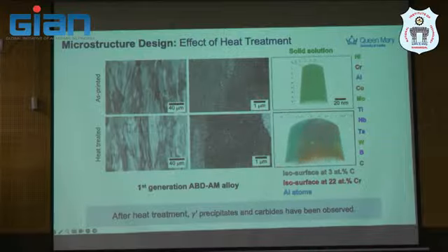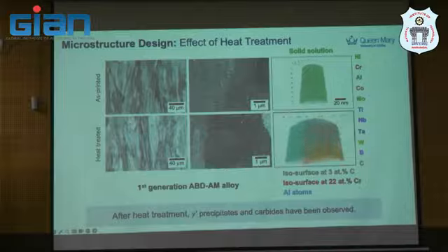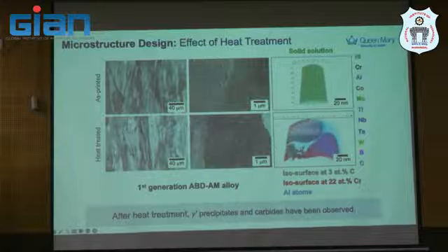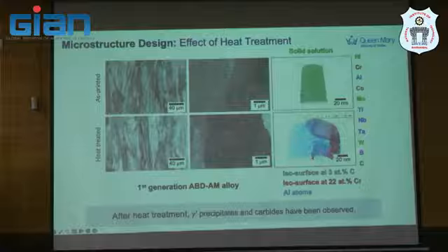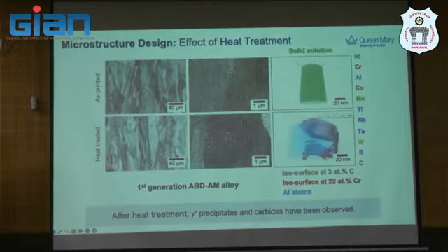We use atom probe to really map the composition in 3D, to see what happened. So there are isosurfaces of carbon, chromium, and aluminum atoms in this one. It starts to form gamma prime, and this gamma prime that I show you is not a defect. This is gamma prime after heat treatment, actually. So you will see not only primary gamma prime, you see secondary as well. But anyway, this needs the right heat treatment protocol to homogenize the structure later. But I leave that for another talk. It's not for this one.